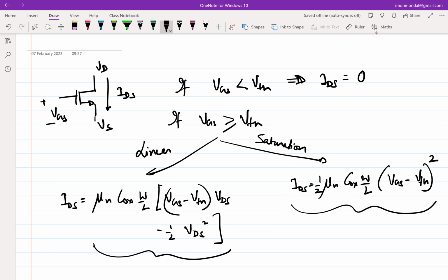So you have these terminals. Let's say this is a black box, and you didn't know anything. Let me call this VD and this VS. You are applying a voltage VDS and observing this current IDS. What will you observe? You will observe that this current doesn't change even if I change VDS, right?